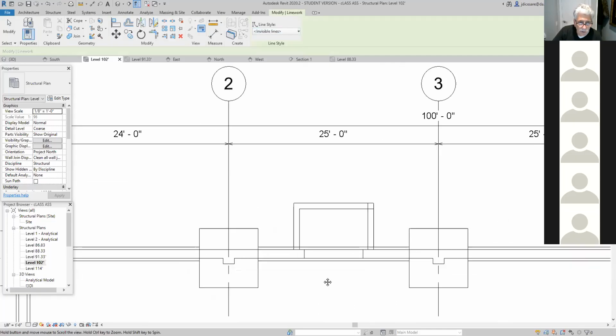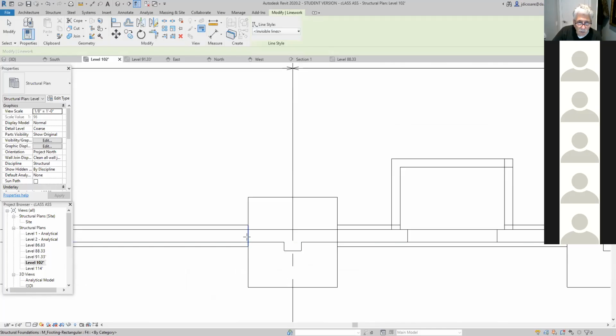And if I zoom in here, you'll notice that this little line should not be there. So I tell the program, make that invisible. Oh, wait a second, how come it's still there? That's because there's an upper edge and a lower edge to that footing, and therefore by clicking it again, it's gone. So that's how you have to clean up the drawing. You have to do it twice because the footing has an upper edge and a lower edge. You have to remove both of them.